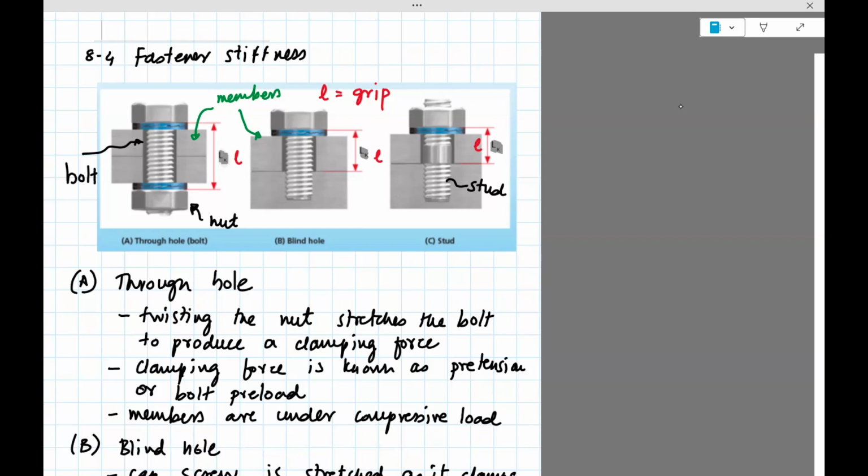You could also have a case where the screws are not fully threaded. So here I've shown both these screws are fully threaded, but there could be screws which are not fully threaded, in which case you need to account for that. So there's a lot going on here, which we'll hopefully tackle in this part. It'll give us a way to compute the forces if you know the stiffness. So stiffness and force are directly proportional, right? Force is K times, or stiffness times the deflection.